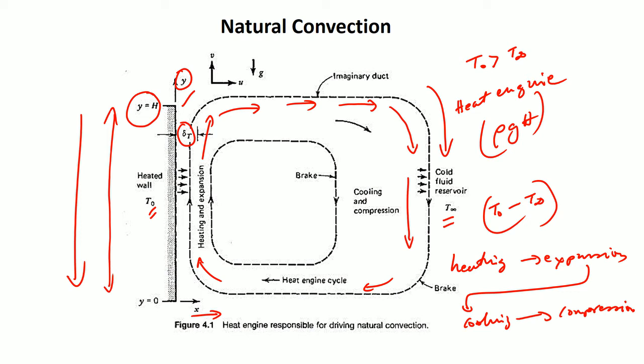So, there is a small region in which the heat is being transferred, that region is basically that delta T that we mentioned, where the heat is transferred from the wall to an adjoining layer of fluid, moves up, gets cooled, sinks, comes back, it completes that particular kind of cycle. Okay. Got it? So, this is pretty interesting, in a natural convection case.